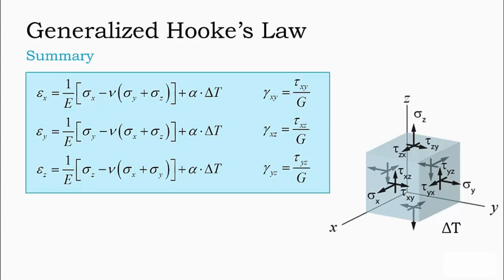This is the generalized Hooke's law that will allow you to calculate the normal and shear strains at a point in a material given the normal and shear stresses. We will be using these equations throughout the course in order to examine deformation in everyday engineering structural elements.